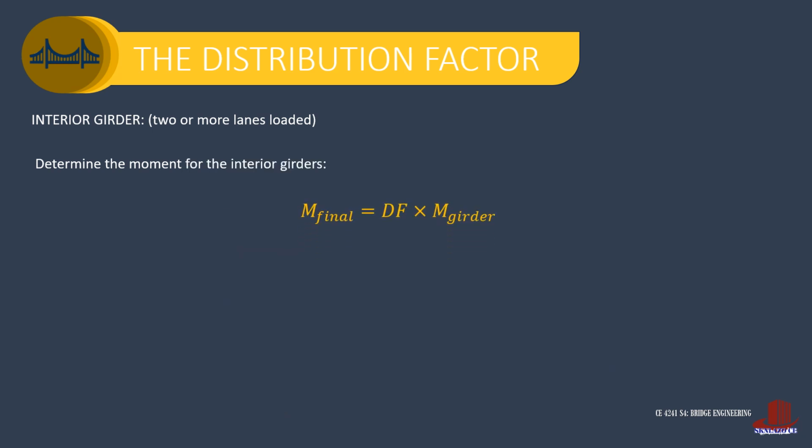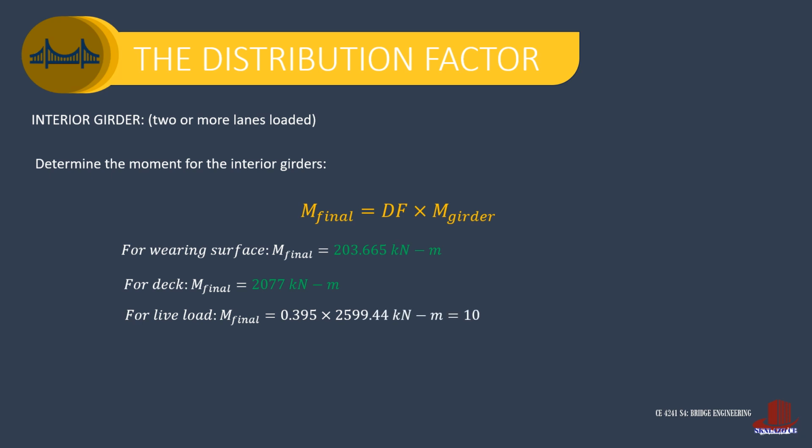The final live load moment is then computed with a distribution factor. However, the moment for the wearing surface is still 203.665 and for the deck as 2077. The live load moment is 0.395 of 2599.44, giving 1026.78 kilonewton meter.